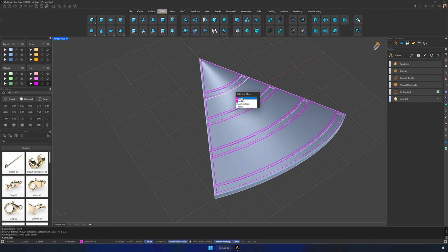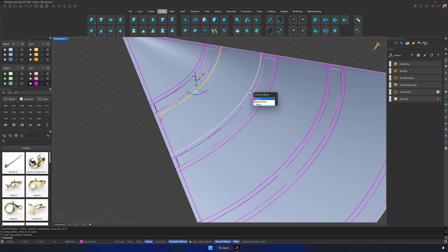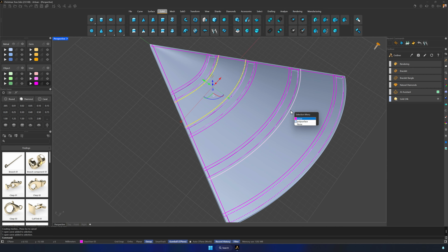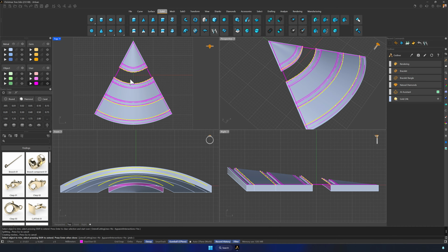Next, select the boundary curves that define the wider top surface and the bottom surface, as shown in the video. Hold Shift to select multiple. Switch to the top view, run Trim, and cut the 2 surfaces, separating the element into 3 parts.